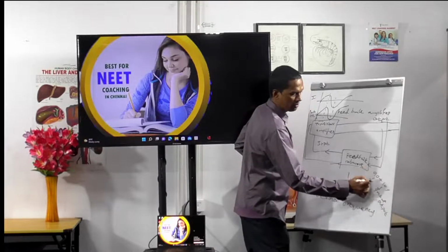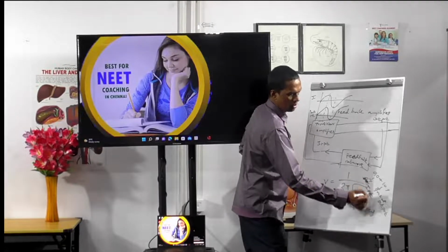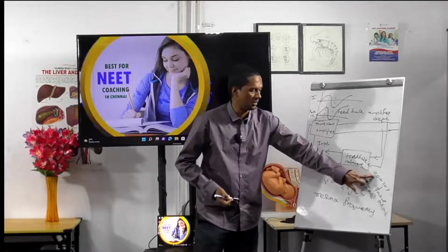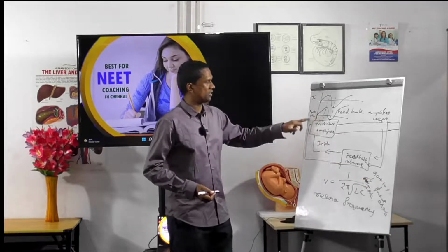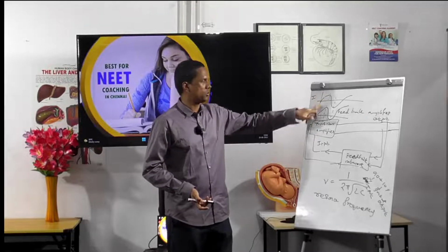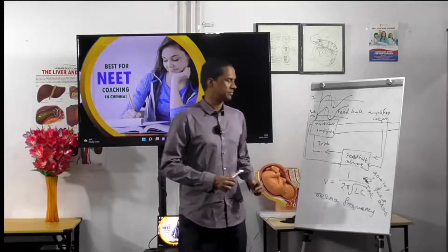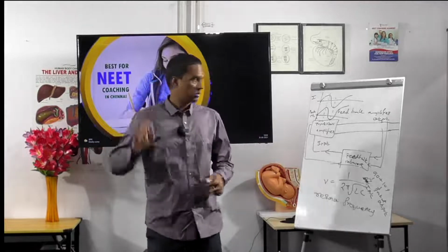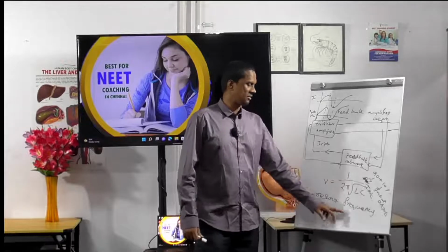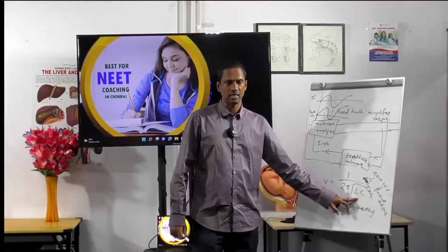This 90% and 10%, both should be in phase. This was the input, which is 90%. This one is part of output, which is 10%. Both should travel in the same phase. So you take this diagram, and frequency is equal to 1 by 2 pi root LC. Resonance frequency is given by 1 by 2 pi root LC, where L is inductance and C is the capacitance.